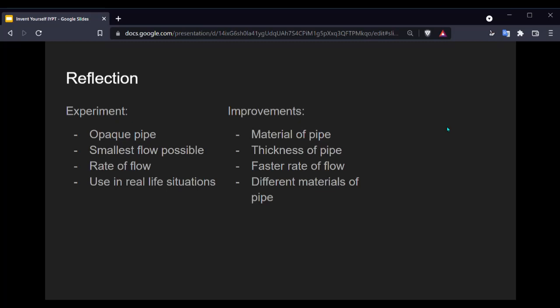Later, we came up with the genius idea of not increasing the temperature, but rather increasing the exposure the water receives to this heat. That way, the temperature would not be too dangerous and the device would still be effective. By placing multiple light bulbs or heat sources along the pipe and covering more of the pipe with black tape, the water is able to flow at a faster rate while still having enough heat transferred to it to be able to be picked up by the temperature gauges. This addition may also allow pipes of different materials, diameters, and wall thicknesses to use the same method.